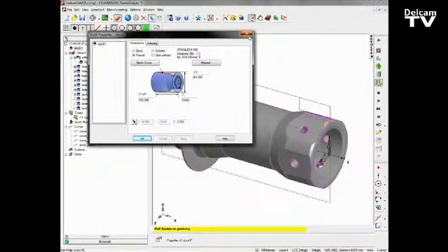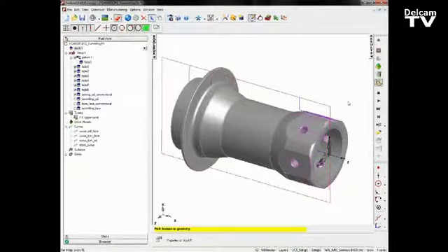So this material is known for when we are turning, the swarf will gather around the turning tool and it doesn't break particularly easily. So if we use a milling type tool or a live tool, we can use the chip breaking to actually snap off smaller chips rather than ending up with long swarf from a turning tool. So this seems to be the best way to attack the part.